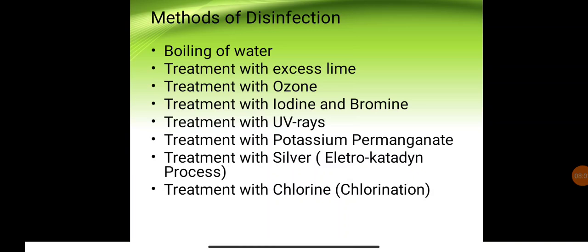What are the advantages of using ozone? It is a very excellent disinfectant, and it is able to remove color, taste and odor from water. With other treatment methods, such as boiling of water or treatment with lime, we cannot remove the color, taste and odor, but the treatment with ozone can.